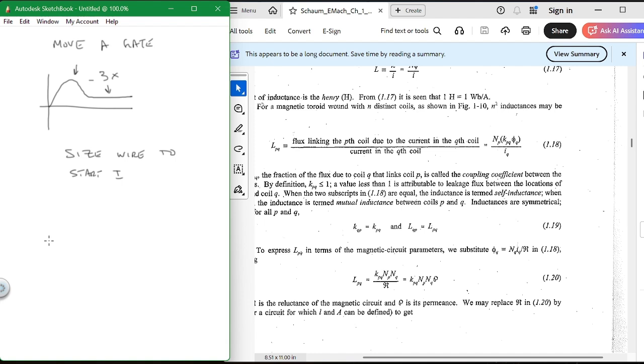So here's the deal. This is the Owens-Corning rule of thumb. If you have a solenoid and you want to run it more than 200 feet, use number 12 gauge wire. Less than 200 feet, use 14 gauge wire. We used 14 gauge wire for everything, pretty much.